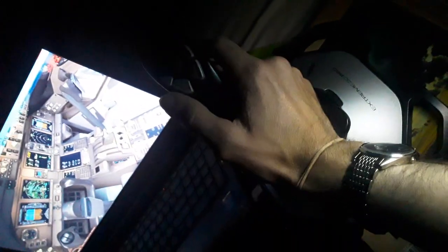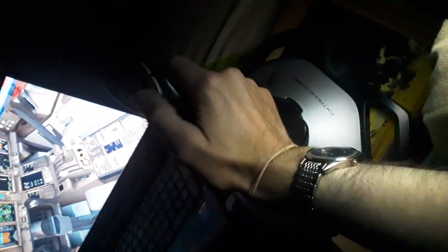So it's a good thing to have all the controls, like the flight controls and the engines together, and the horizontal trim. You can see the horizontal trim of the horizontal tail over here. I press this switch, I can trim up and trim down the horizontal tail of the aircraft.